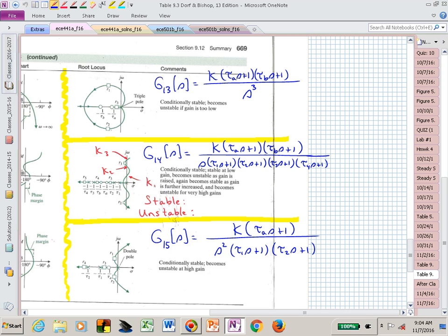In this particular diagram, you have 3 poles to the right of 2 zeros. Those squares are the squares where you might have closed loop poles. And in this particular case, they've selected the gain k to get you into the left half plane of those conditionally stable poles that are bouncing back and forth between the left half plane and the right half plane. That's what they mean by conditionally stable. If the gain is not right, if it's not the Goldilocks value, you may be unstable. And you're trying to now find that range in one of your homework problems.